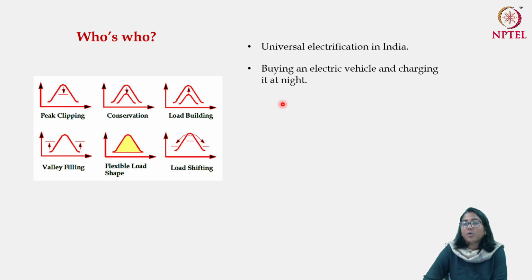So this activity was earlier not present in your electricity consumption profile, but now this is going to be added. Now assuming that night time is your off-peak period, if you carry on this activity in the off-peak period, then you are contributing to valley filling, so that the rest of your load curve remains unchanged, whereas you are actually increasing your energy demand during the off-peak period.